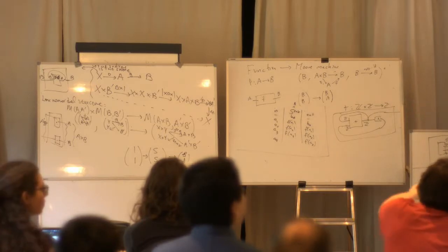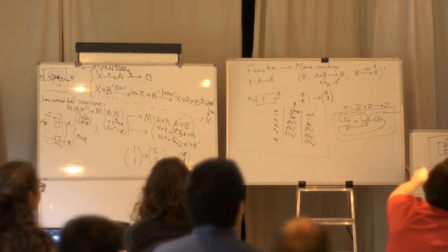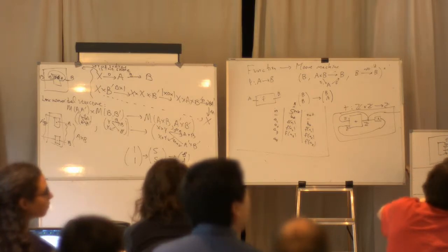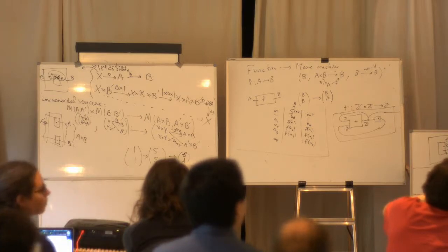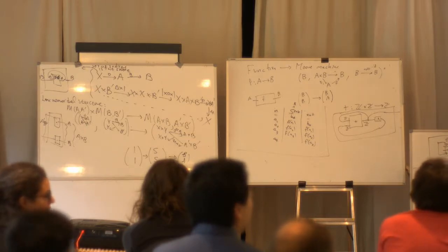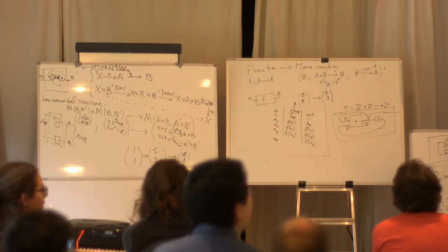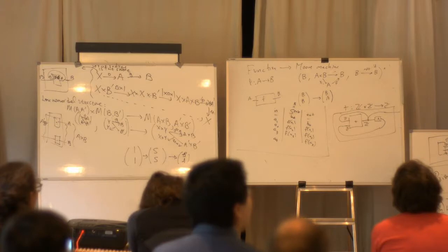I mean, in the end, you constructed a signal flow graph that does Fibonacci, no? I guess so, yeah. I mean, this looks like the signal flow graphs that implement Fibonacci. Signal flow because they're functions. It's all Fibonacci. But the graphical language is quite different. Here there are implicitly the registers, whereas there they are explicit.